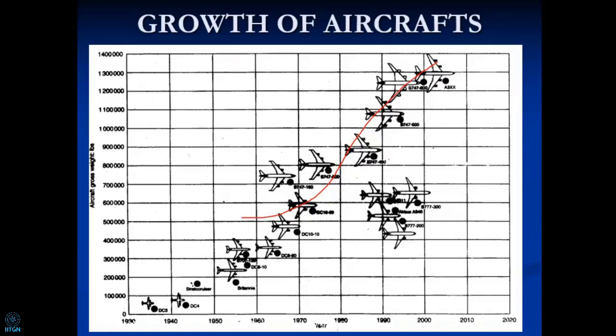Now, can the manufacturer keep making the aircraft larger and larger? Any idea on this now? Can the aircraft manufacturer take a sumo decision: okay, I'll make a new aircraft with heavier loads? Can he do this? Hypothetically, he can do it. But then the heavier aircraft, depending on the kind of aircraft he's making, requires a longer length of runway. So you can always design a good, bigger aircraft, but it can't land on the existing airports.